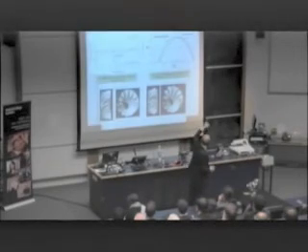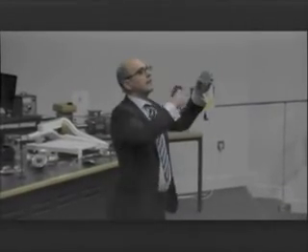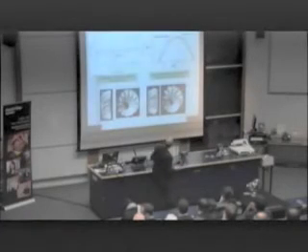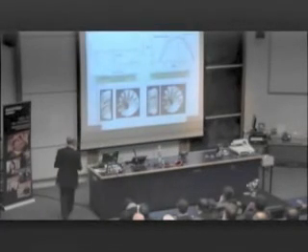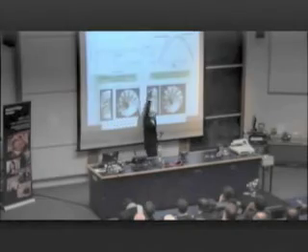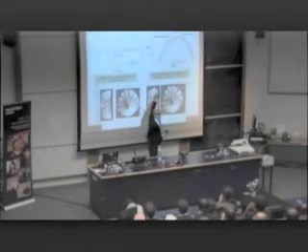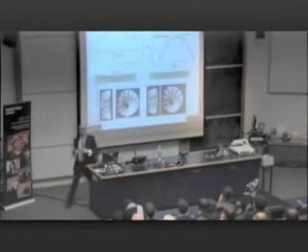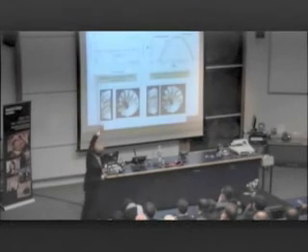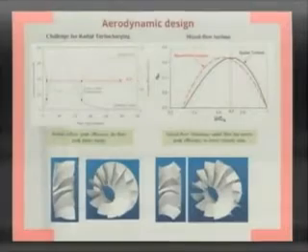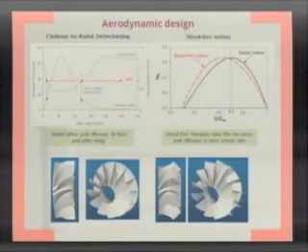Had a design, radial turbine, which I'm holding. I'm going to change the blades, and I'm going to make it into a mixed flow turbine, where the flow comes at an angle. And I shift it to the left, and thus I move the peak efficiency elsewhere. I get the mixed flow from the radial. The flow comes in along that diagonal. I'm indeed capable of doing that, and if I do so, I move partially that peak in the area of greatest energy potential.